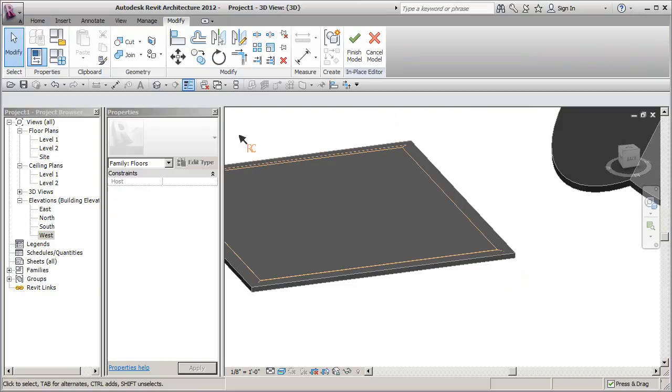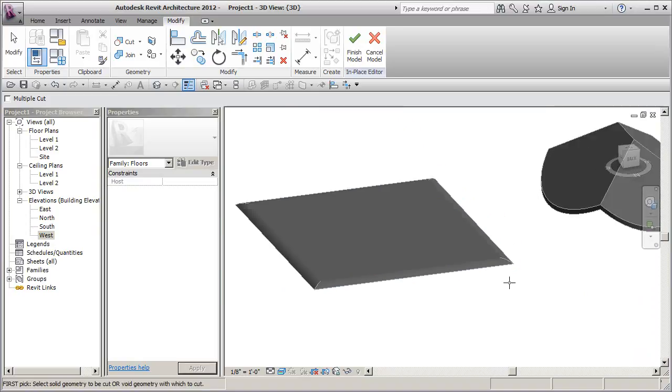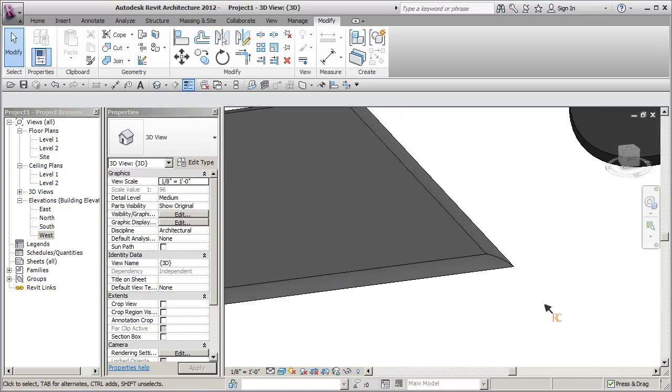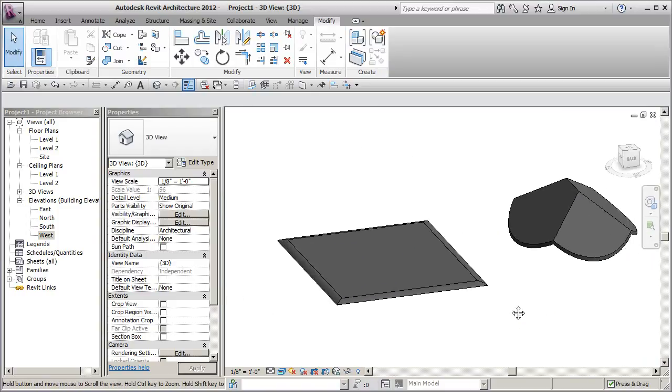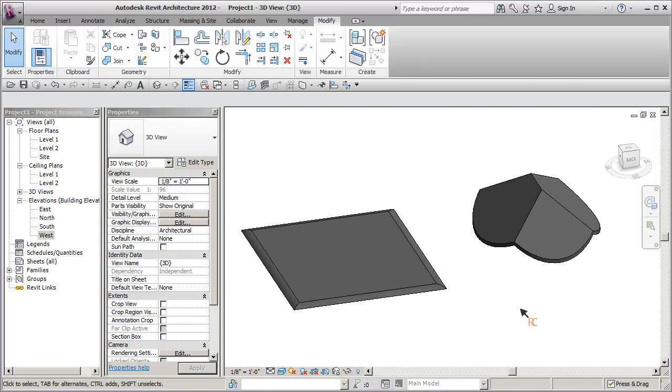Boom. Click out. Now I have to cut my geometry. Cut from the floor. This guy. And cut void sweep from the floor. There we go. You have to just use your tab key and then finish. And there I've got a floor that looks like this instead. You could also maybe achieve that with the floor object itself. So there's a couple more tips on using cut geometry with roofs and floors, as well as with walls, all by using void objects.